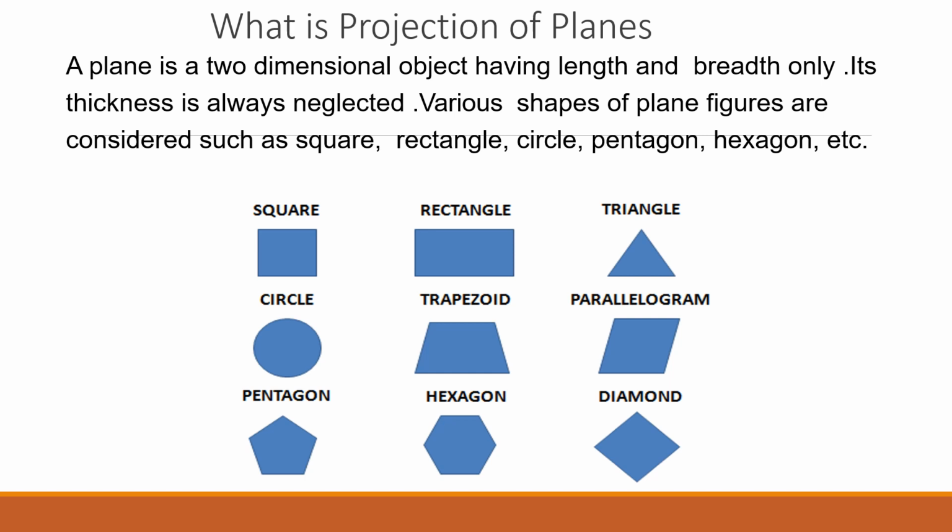And before going into these things, for drawing your pentagon and hexagon, you should be knowing the angle between the sides. So if at all you know the angle, then it is fine. If at all you don't know the angle, you can calculate the total angle. Suppose you consider a pentagon or you consider a hexagon, you can calculate the total angle by using a very small formula, which is given by 180 into n minus 2. Okay, so this gives the total angle of the polygon.